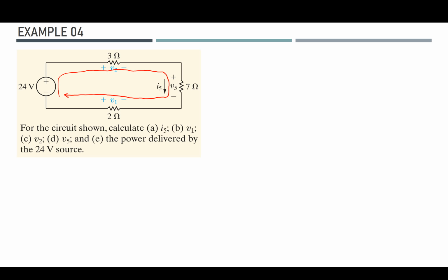I know that all the current in this loop will follow, like then I will have these I2, because the current shall flow from plus to minus, so I have a higher potential here. And here in I1, again, I1 is flowing in this direction, which is opposing I5, but it doesn't really matter, because from the KVL we will always get the correct equation.